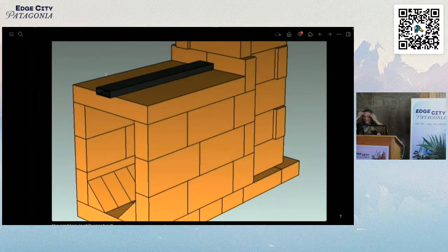I forgot to tell you one important thing. In order to make a small-scale, or it doesn't matter actually, a bigger-scale pyrolysis stove, you need two chambers. One must be heated, so the pyrolysis chamber must somehow be heated. In one chamber you must have this complete burn. In another chamber you must control the amount of oxygen, a different task, which is vice versa. You must not burn, you must heat and not allow oxygen.